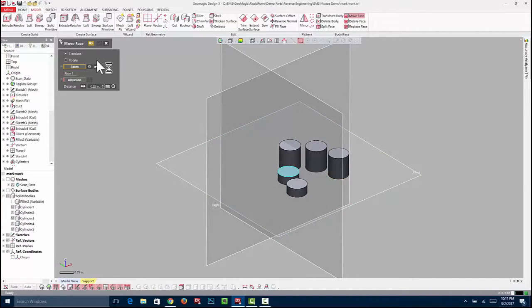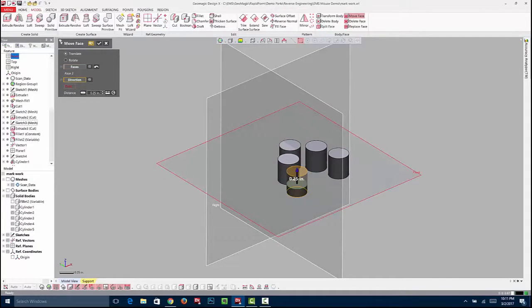But since we only have a few of these to do, is this faster than just drawing the circles? Probably not, but just to kind of show some of the different tools. The goal here is, what we're trying to show here is you can extract primitive shapes, cones, cylinders, and things like that right from the scan data.